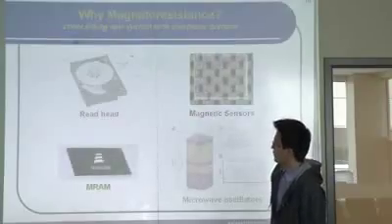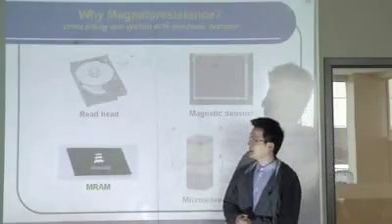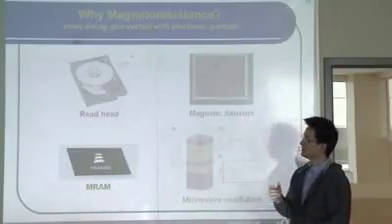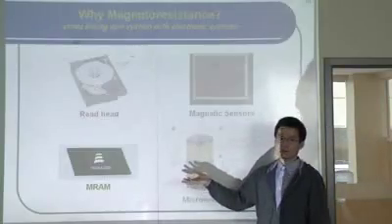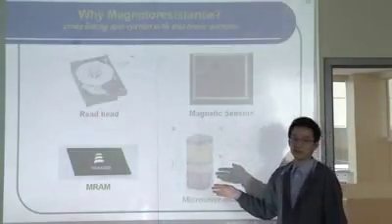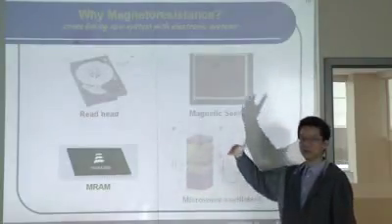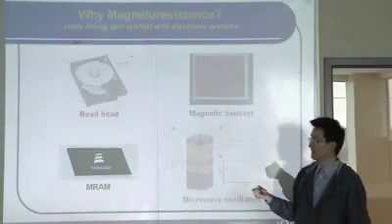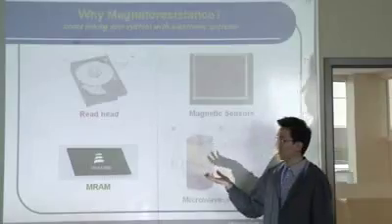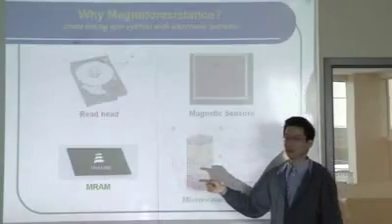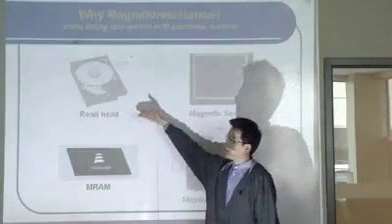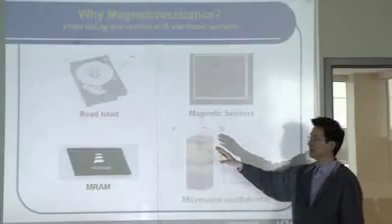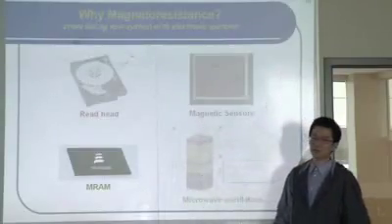And one of the latest developments in magnetoresistance devices is the magnetic random access memory. In such a memory device, the data you put in the memory is non-volatile. It will stay there essentially forever without any power because it is stored in magnetic units. And the device has a high density and a very high speed. Essentially, it has better performance than any other memory technology. For example, it can integrate the DRAM, the hard drive, and flash into the same unit. This type of memory is usually referred to as a universal memory.